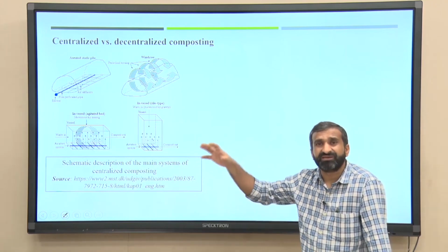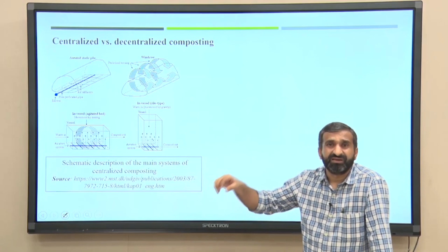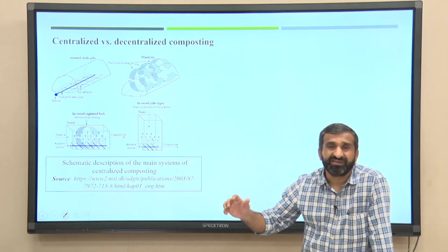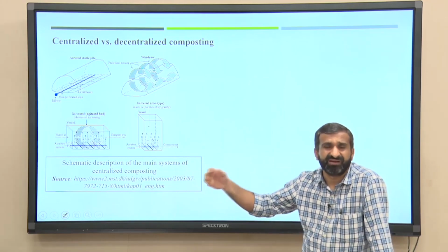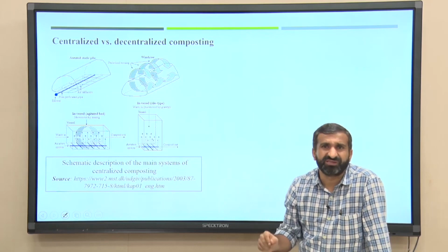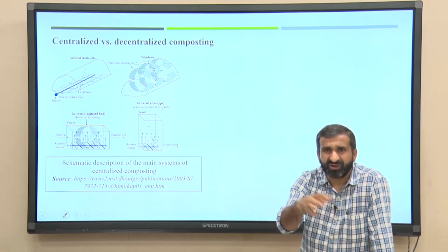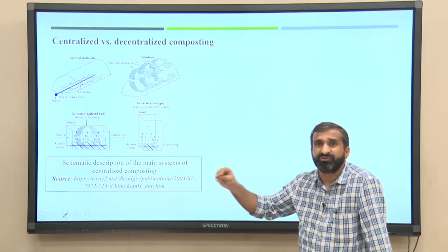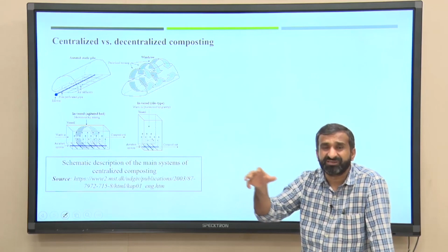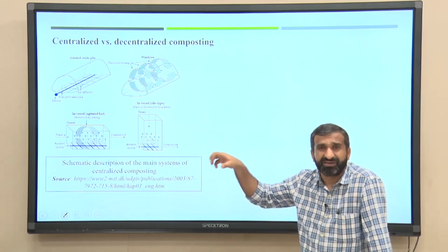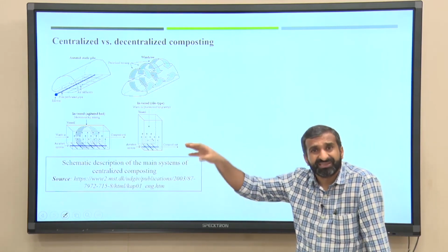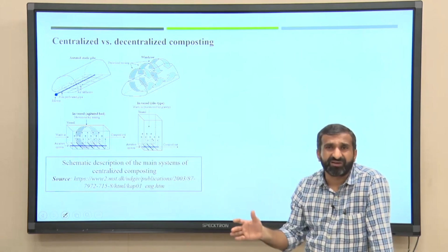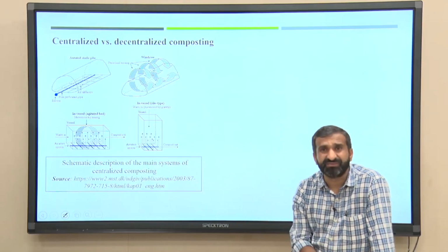But again, the problem at one particular location, if you are receiving 200 tons, 300 tons in a day, is how big an area will be required, and you can't just rely on the windrow system. You know that there are a lot of issues regarding the windrow system, and you also are required to produce good quality compost for sustainability, because that product has to be sellable in the market, otherwise the entire compost plant can't be sustainable. So